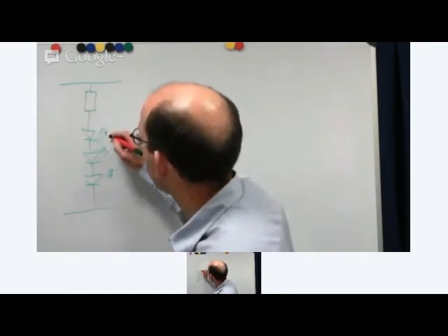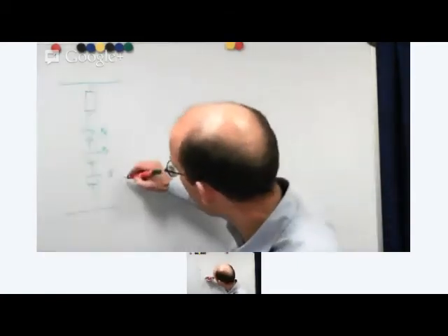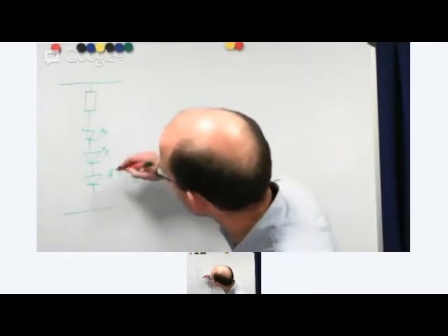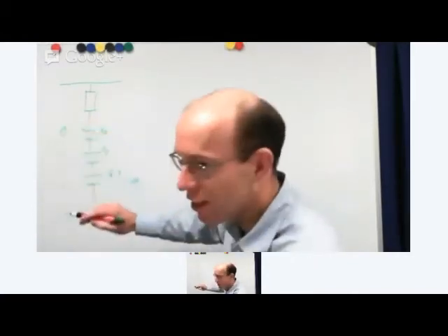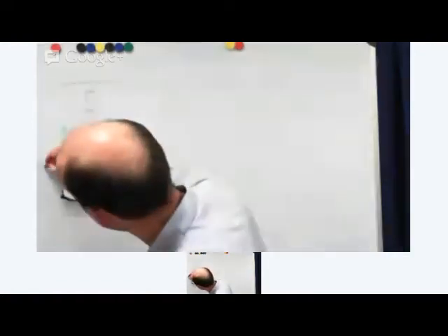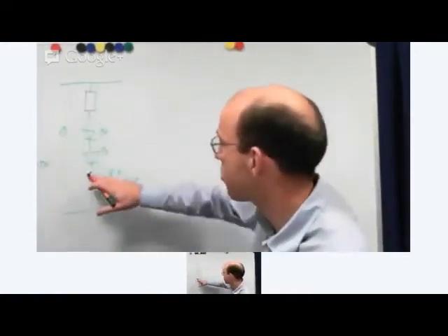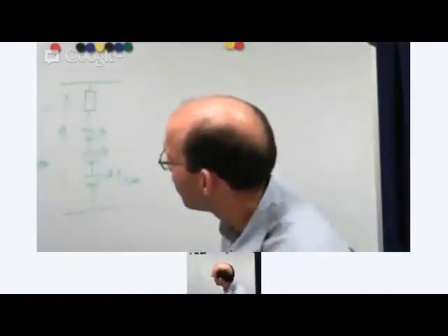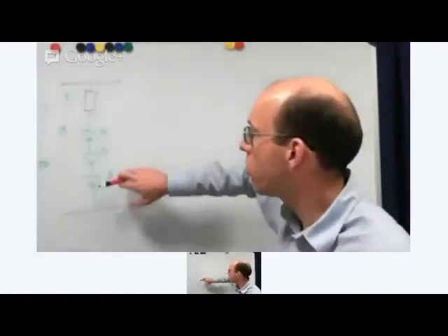Now, suppose on each of these that we've got 3.3 volts dropped across each LED. Then across the 3 LEDs, give or take to the nearest 0.1 of a volt, we've got 10 volts across that, so 3.3, 3.3 and 3.3, which leaves us with a couple of volts there. And again, we can do the same maths and we can work that out.